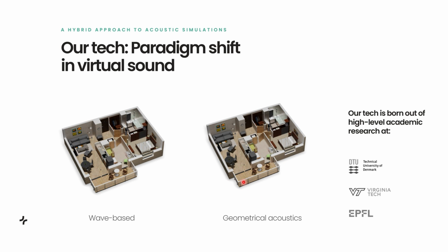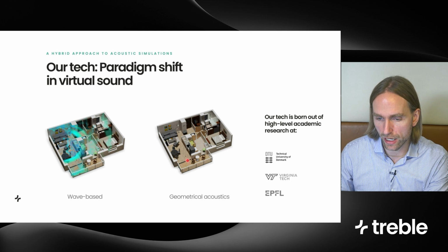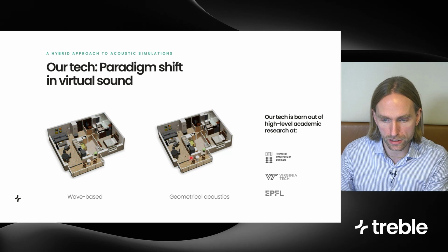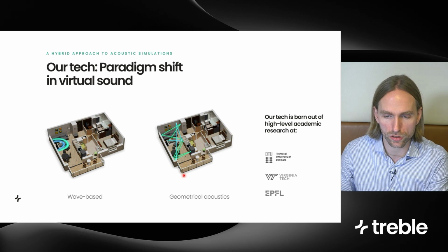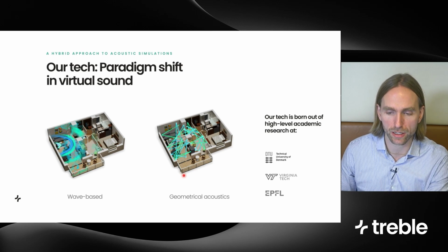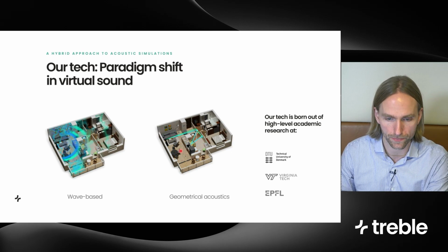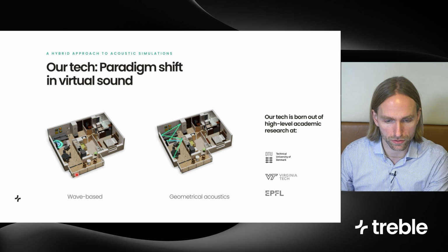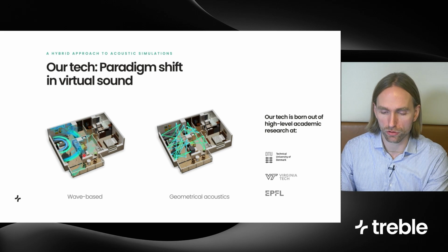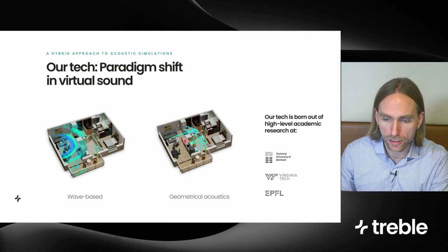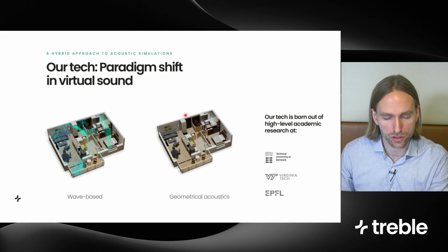Geometrical acoustics is inherently a high frequency approximation, so it's a fair way to model high frequency sound, but it breaks down at lower and mid frequencies because it's hard to model acoustic phenomena like diffraction, phase and interference and so on with geometrical acoustics. Wave-based methods, on the other hand, inherently capture these complex acoustic phenomena, so it's natural to consider combining the two. The reason why this hasn't been done so much in practice to date is because the wave-based part has always been so computationally heavy.